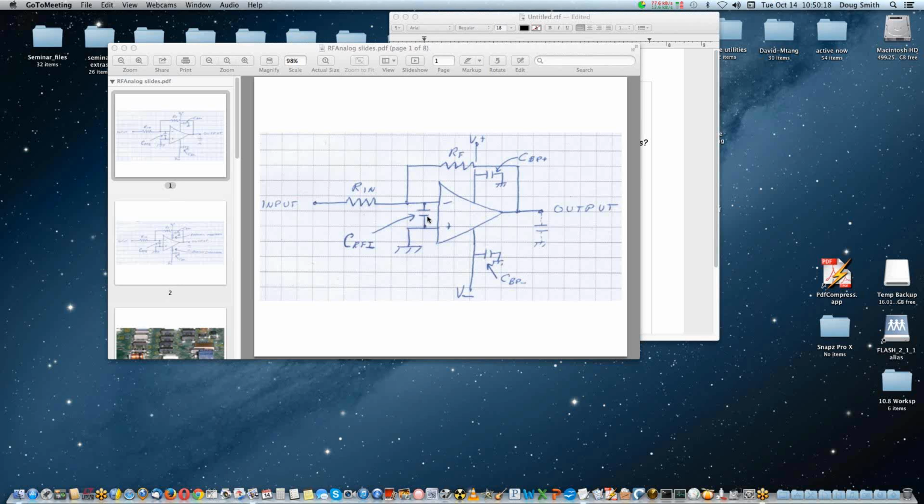They usually did such a wonderful job of explaining what they did, right? So now you don't know anything about this circuit, and you get an RFI problem on an op-amp. Here's my shortcut of doing a simulation or a calculation. You put a capacitor, find out what value gets rid of the RF, and then you keep going and find out what value causes an instability. And if you're 1/4 of the instability, and it still fixes the RF, you're probably okay. That's the poor man's quick solution, or the quick solution when the boss is breathing down your neck.